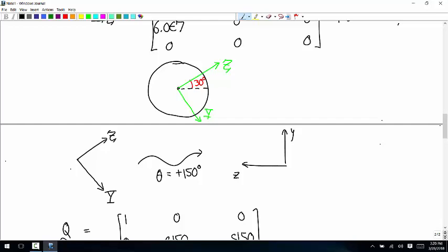And I suppose also if all you have is stress due to torque and bending, or stress due to bending and or tension, you also don't have to rotate because rotating the coordinate system doesn't affect the x normal components, because both of these two coordinate systems have the same x axis. But I think you might want to just do it because you're going to have to do it sometimes.